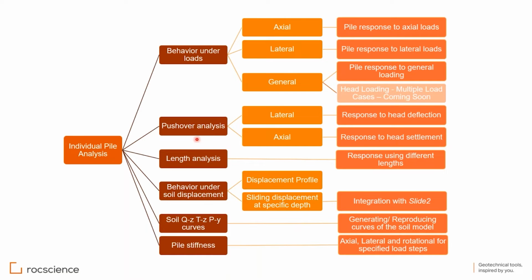We have in the individual pile analysis what is called the pushover analysis. The pushover analysis is very good for estimating the load-settlement or load-displacement curves of the piles. Before you start the test, you expect something, and after the test you can calibrate your soil parameters to simulate the test with the same curve generated from the pushover analysis. We also have length analysis. If you don't know at which length the pile will behave better, you can run a sensitivity analysis on length.